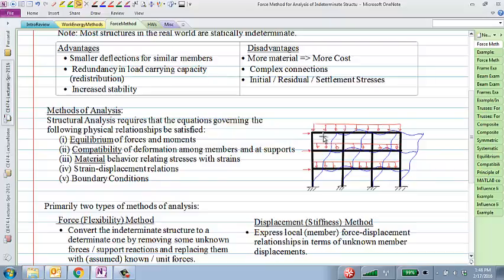3, right? Yeah, because X component, Y component force, and internal bending moment, those would be the new unknowns I've created. So 1, 2, 3, 4, 5, 6, 7, 8, 9. 9 is the total number of cuts that I'm making, times 3 unknowns, 27 total unknowns we have. How many equations do we have?